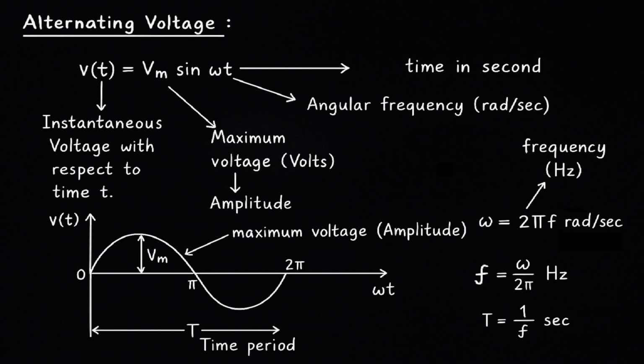As one pole of the magnet moves towards the wire, the voltage climbs. As it spins to its peak position, the voltage hits its maximum. As it spins away, the voltage falls back to zero. Then, the other pole of the magnet swings by, and the voltage does the same thing, but in the opposite direction, it goes negative. This continuous, circular motion of the generator creates the perfectly smooth, repeating rise and fall of a sine wave.